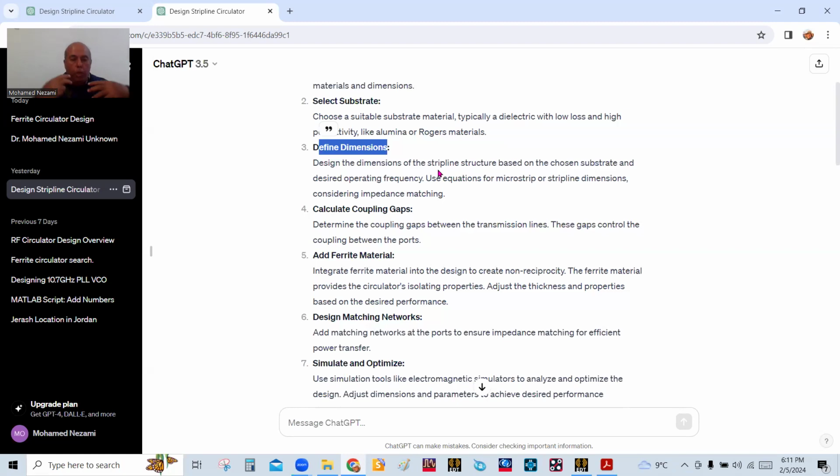But still, we will start with the equations, plug in numbers, and get values that are going to be messy; it will not work. We go in, build the structure in 3D EM, and then go back and forth until we get it to work, either iterating by common sense, or parameterizing and optimization, or sweeping. I use sweeping, as I will show you, because there aren't that many things to really design. Depending on the frequency, the materials, the magnet and the ferrite, you're going to have basically the radius of the ferrite.